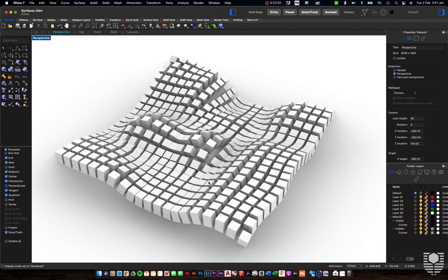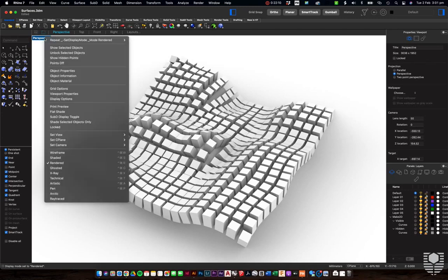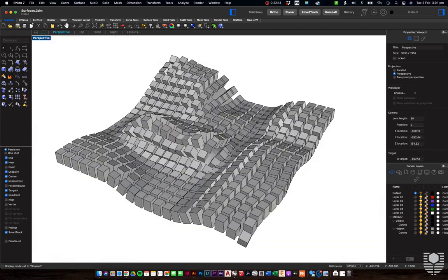the camera or not, we lose a lot of information. We get what's called whiteout, we end up with some of the image, but not all of it. And some parts look really good and other parts don't. And too much for my liking gets lost. So what I usually say is that shaded is better because it also provides the line work. So anywhere that would usually be whited out, we end up with line work, which kind of catches the difference and allows us to see both where we have shade for curvature, where the blocks are opening, but also the quote dead spots, end quote, as well. So you want to make sure you're using shaded instead of rendered when you're taking these out into Illustrator.